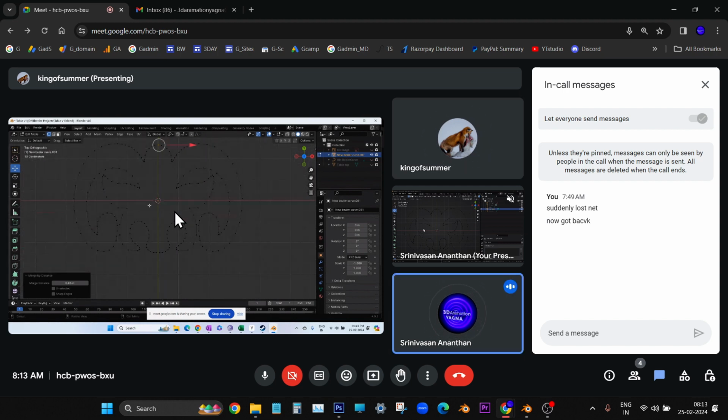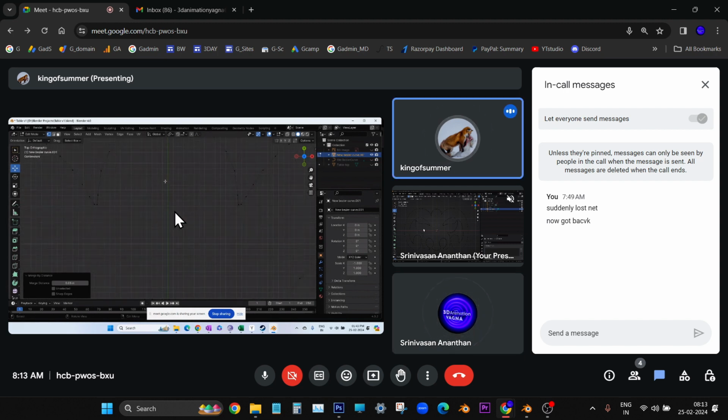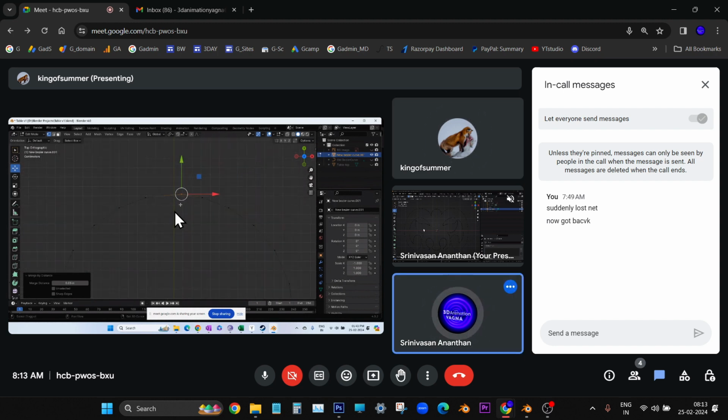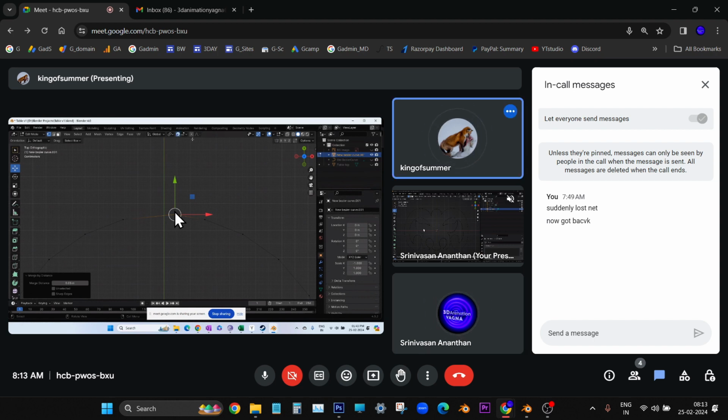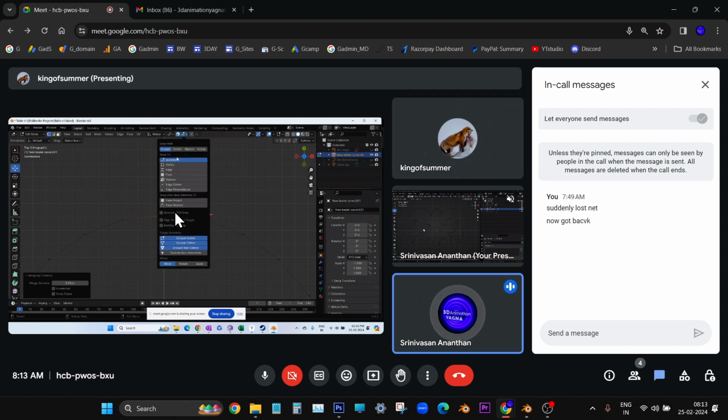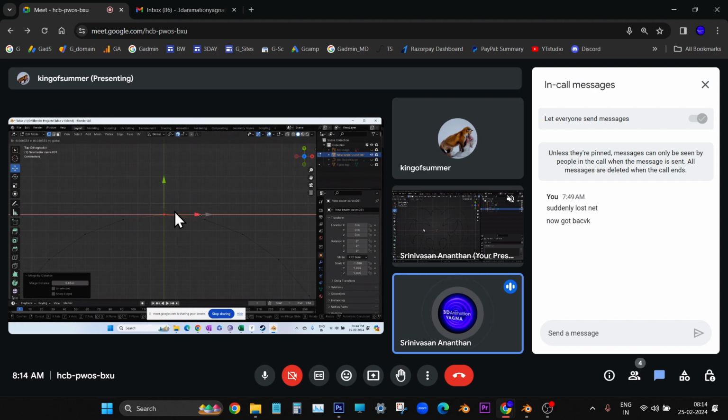No, no. Bring in, zoom in, zoom in. We have to switch on the horseshoe magnet and go to its menu, and switch on the absolute grid snap. Now press escape to escape the menu and use this x-axis handle to move it leftwards. It will snap on the green color.